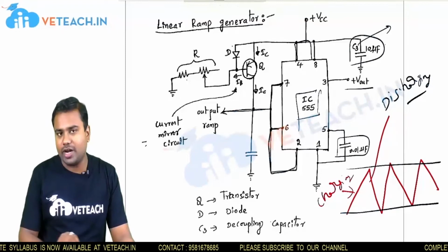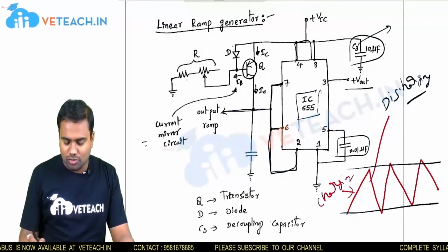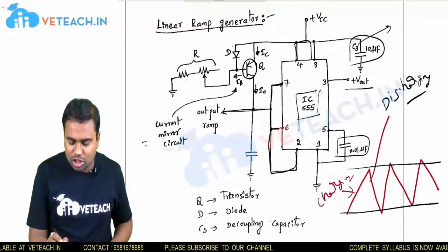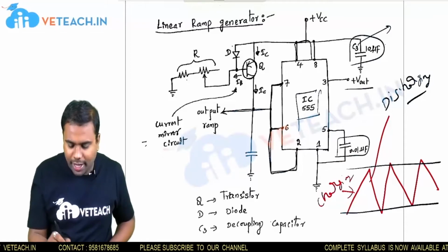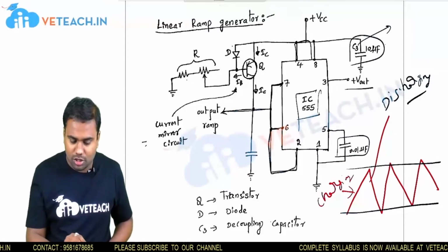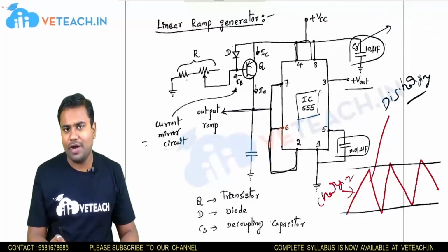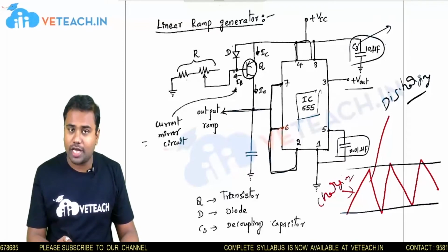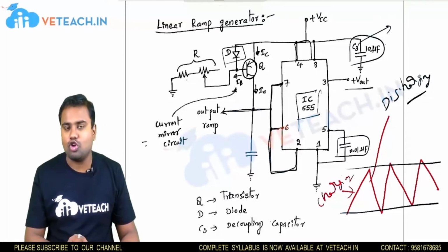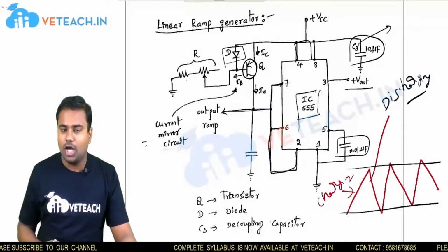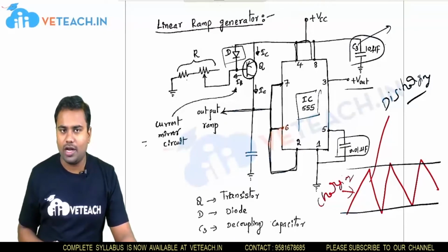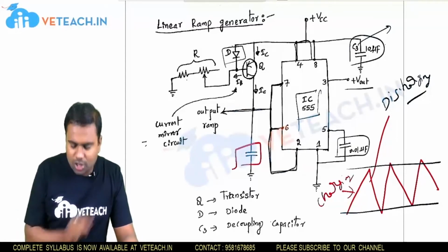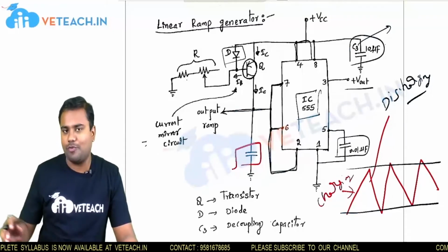Here I am going to connect one capacitor C3, and this will be connected to VCC. Later I am going to connect my transistor to the pin number 7 shorted point, with one pin for VCC, and the base will be connected to the variable resistors. Here I am going to connect one diode also. So to give the ramp signals, I am going to connect this type of structure. This capacitor is the one which is going to charge and discharge in the form of a ramp signal.